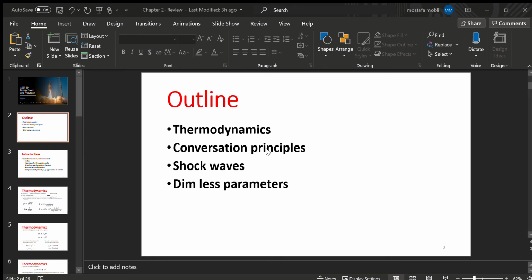Okay. So if you're dealing with a single atom gas, monatomic gases, the only motions you're going to get is a translational motion in 3 spatial directions. Which means that your degree of freedom is going to be 3. Okay? So 3 plus 2, 5 over 3. Your gamma for monatomic gas at normal temperature, that's very important, is going to be 1.667. Okay?